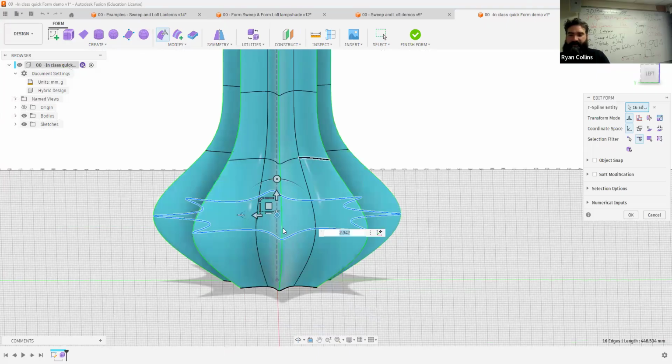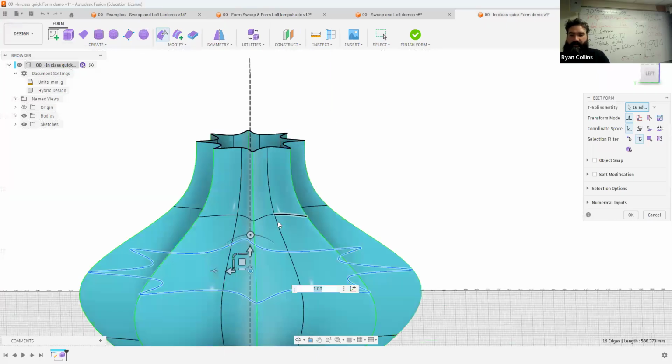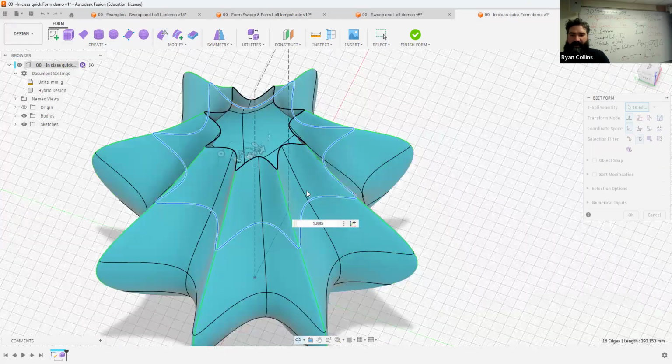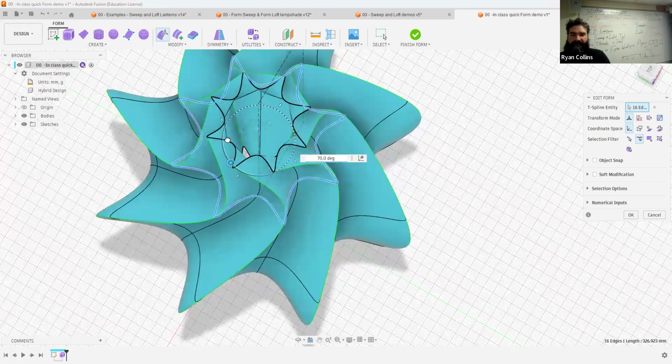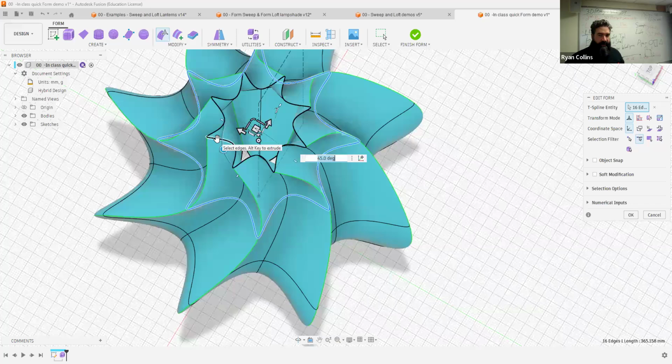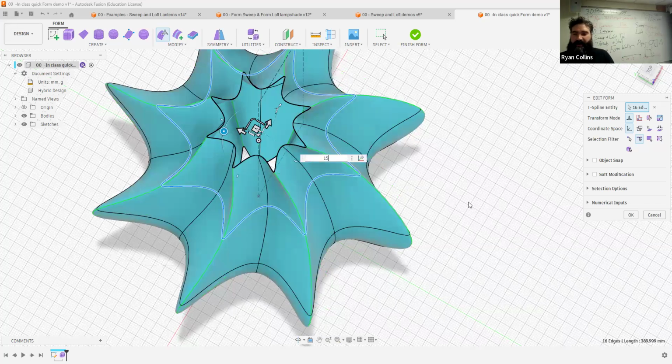Sound effects are up to you. Scaling back and forth, or from above, I can rotate, but be careful. You go too much, self-intersection, utter collapse. So don't go too far with it. That's why we're doing like 15 or 20 degree increments. I would do this numerically just to kind of keep an eye on it.